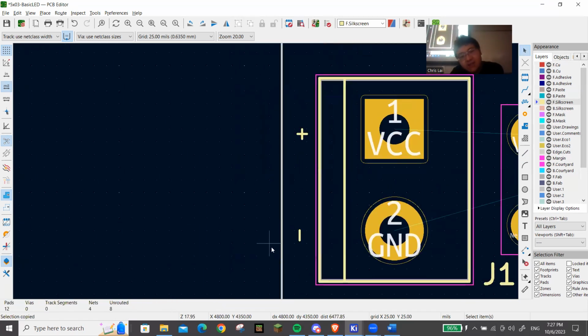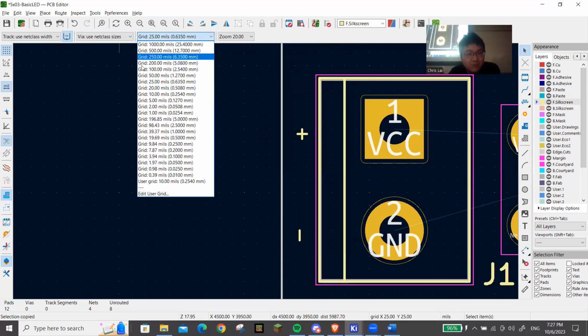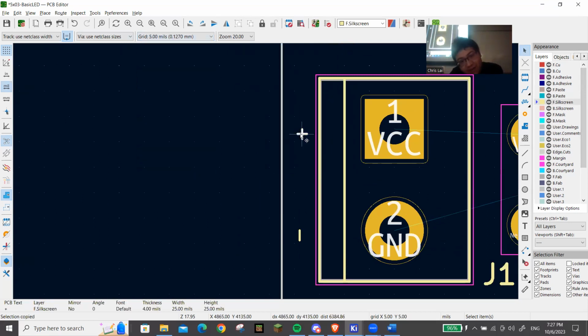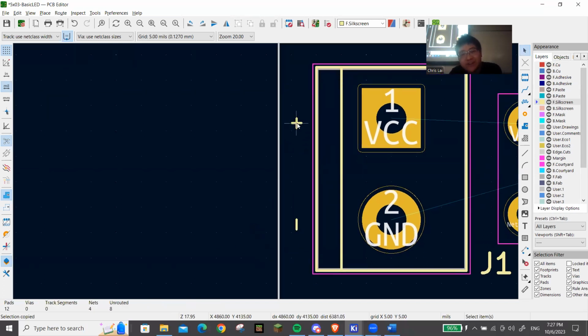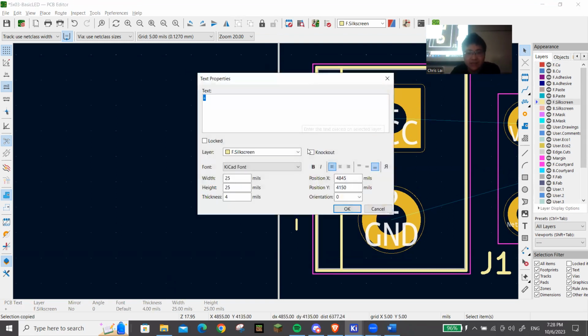And you know, this isn't aligned correctly, but you can spend more time making sure that everything is aligned properly. I've spent so much time on my own just making sure that things are centered and whatnot. It's an art. I have a question. How can I see my PCB, Henry? It's Alt-3. Once you're in this view, press Alt-3, and you should be able to see your PCB in 3D.